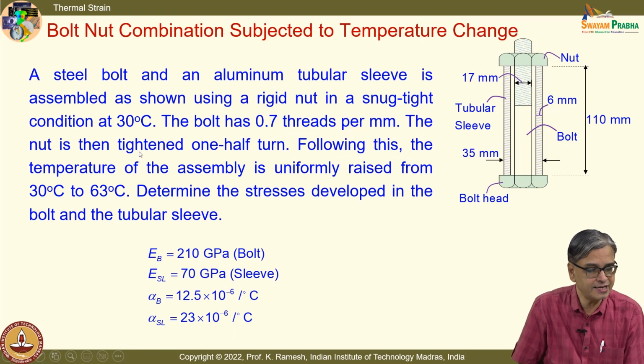And what is seen here is, initially the bolt nut is tightened snug tight, and the nut is then tightened 1/2 turn.